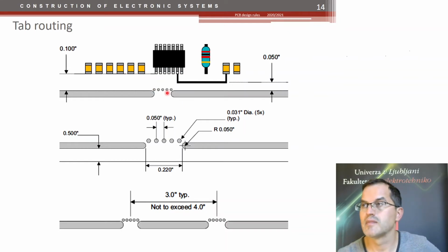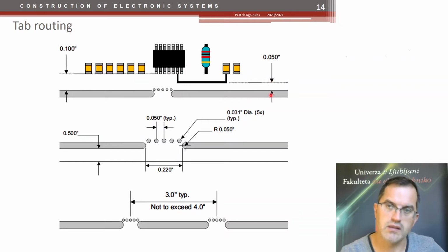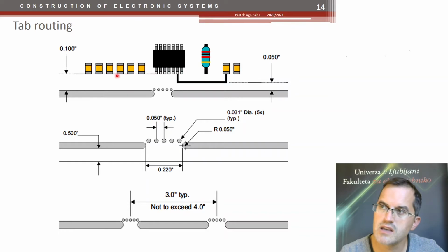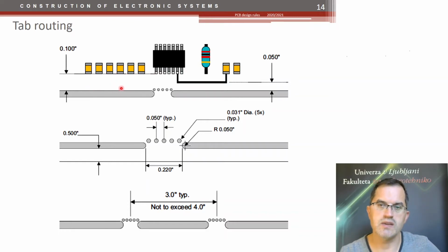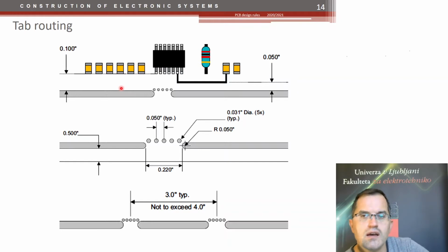And you have to follow some rules again that are telling you how far from the edge you can go with the copper and with the components as well. Because being very close to this edge means that the manufacturer has to follow more strict tolerances, and that means that the PCB would be expensive.